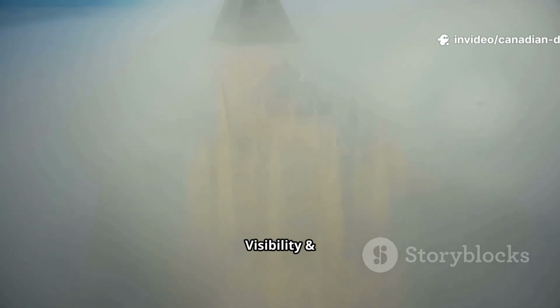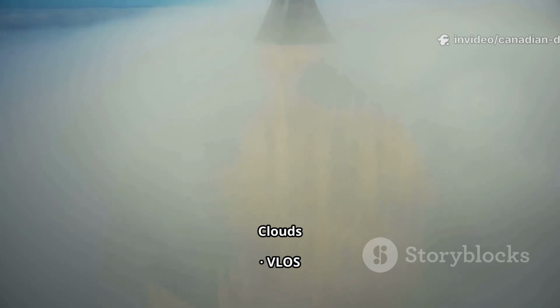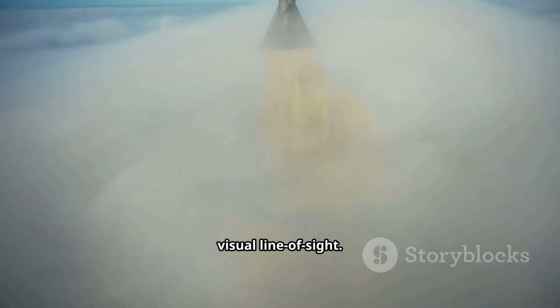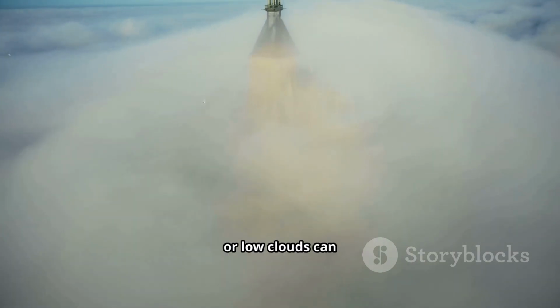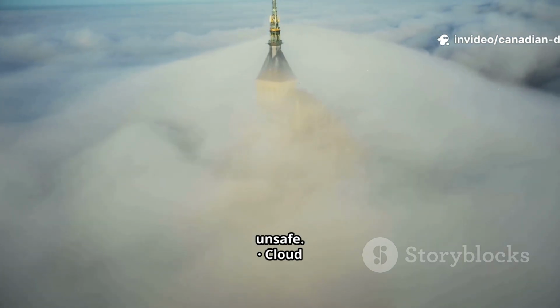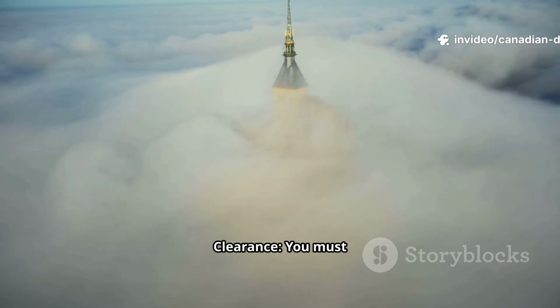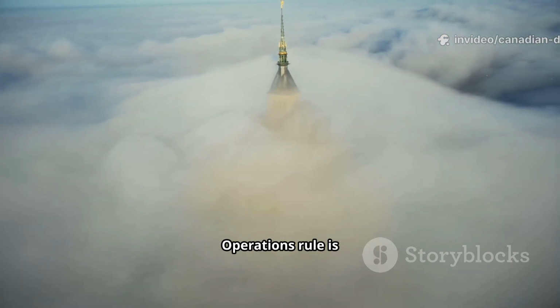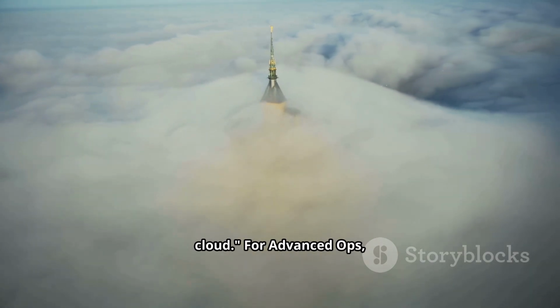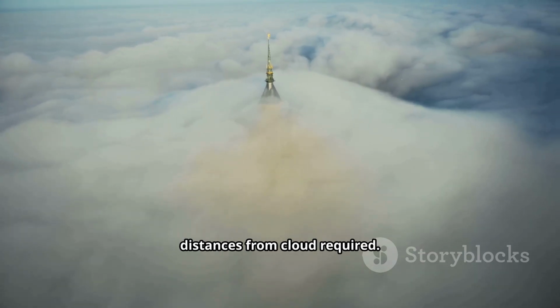C. Visibility and clouds. VLOS requirement: by law, you must maintain visual line of sight. Fog, mist, haze, or low clouds can obscure your view of the drone, making the flight illegal and unsafe. Cloud clearance: you must stay clear of cloud. The basic operations rule is effectively, don't fly in or near cloud. For advanced ops, there are specific distances from cloud required.